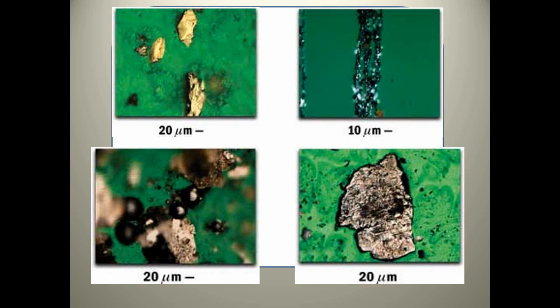Look at some of these slides. These are slides under a microscope. And that's another thing, too. If you're thinking about buying a microscope, you can put drops of oil underneath it at 100 power, and you can look at those drops, and you may see particles like this. So these are little 20-micron particles in the upper left-hand corner. These are 20-micron particles of brass that were in a sample. This is from analytical photography. These are 10-micron particles of metal wear that was in a gear oil.